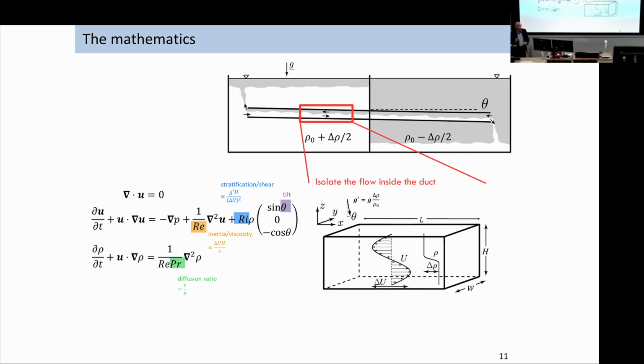These are three non-dimensional parameters. And we have a fourth non-dimensional parameter, which is a Richardson number, which is essentially the buoyancy times the height divided by the velocity difference squared. It turns out in this system, as I'll explain, that number's fixed, so it's not really a parameter. So we have three non-dimensional parameters: the Prandtl number, which reflects properties of the fluid, and then the Reynolds number, which is essentially the density difference, and the angle of tilt. So it's a very simple system with two controllable parameters if you fix the fluid.